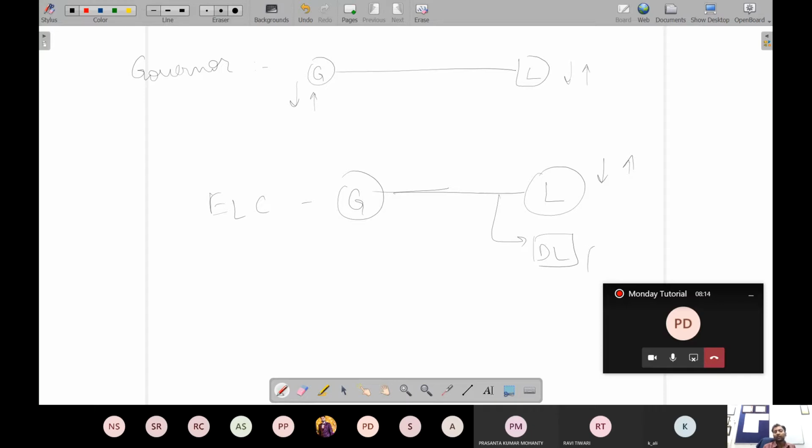This keeps generating as it is. But these dummy loads can be introduced in the system if the actual load is going down. Ideally, the generator can be sized according to the rated load so that even in normal operation there is some dummy load in the system. So the generator can be slightly oversized that way, in case you want control on both sides.